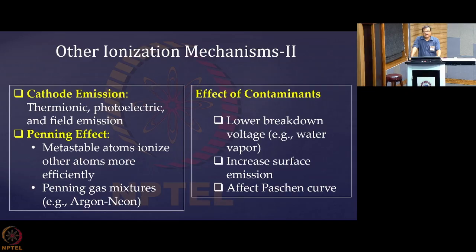When you introduce just 2% of thorium oxide in that as impurity, the ionization potential, not ionization, that work function gets lowered below 3 electron volt. So that is the power of this impurity in lowering the work function of a material which is supposed to emit electrons. So, impurity plays an important role. Sometimes they are very beneficial for the electrodes to emit electrons.